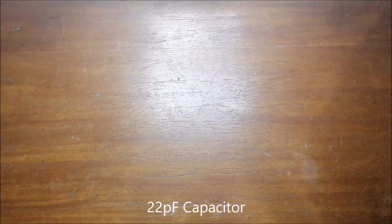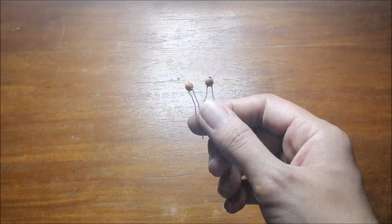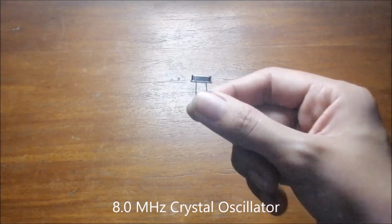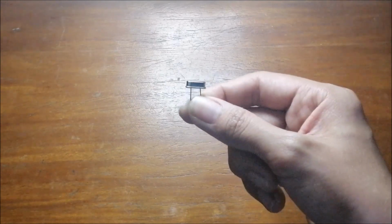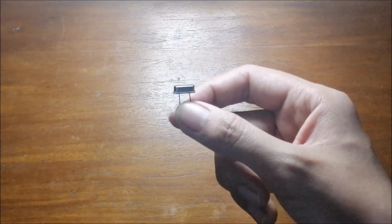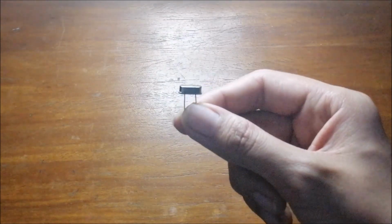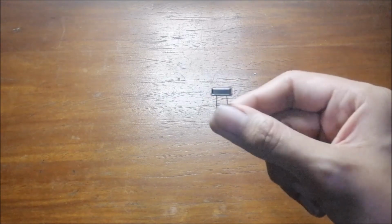And then also you need to have a 22 picofarad capacitor for your external oscillator. And then last but not least, you need a crystal oscillator. This is an external oscillator. Why do we need crystal oscillator? Despite our microcontroller having its own internal oscillator, it's much preferable to have an external oscillator, particularly crystal oscillator, because this is a lot more accurate. So this is just for our clock. What I have here is around 8 MHz.